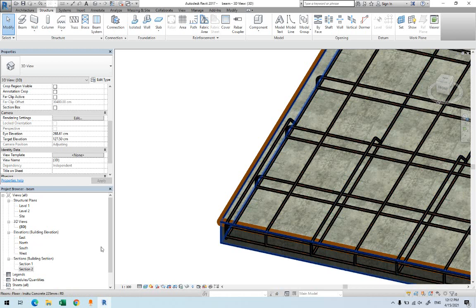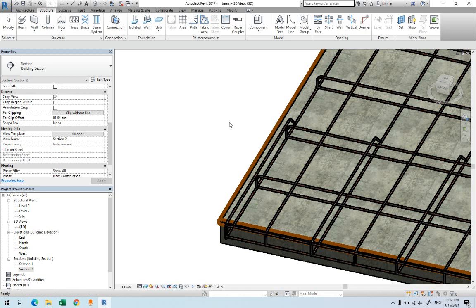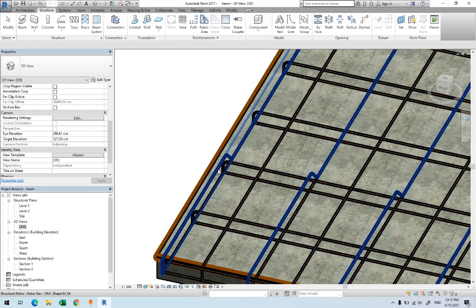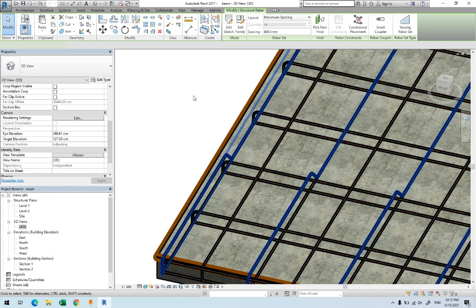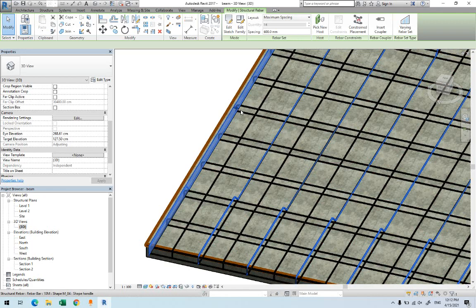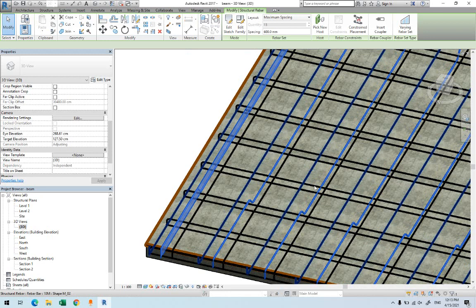So in order to make this one easier for myself, I can go to 3D, hopefully I can change from 3D, it might be easier here. I can select the bar, because there will be grips that I can use. This is the bent up bar, I have it here. So let's see the grips, this is the grip, I have it. So I can manage this to move them in a way that I have it here first. Then I can go to the section to place them exactly at the location.